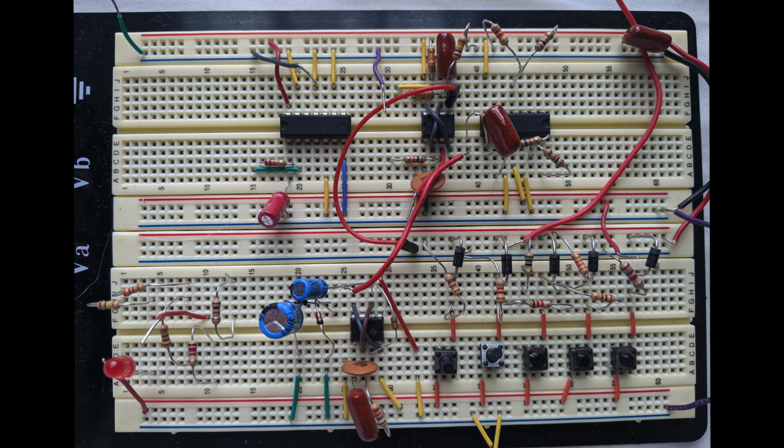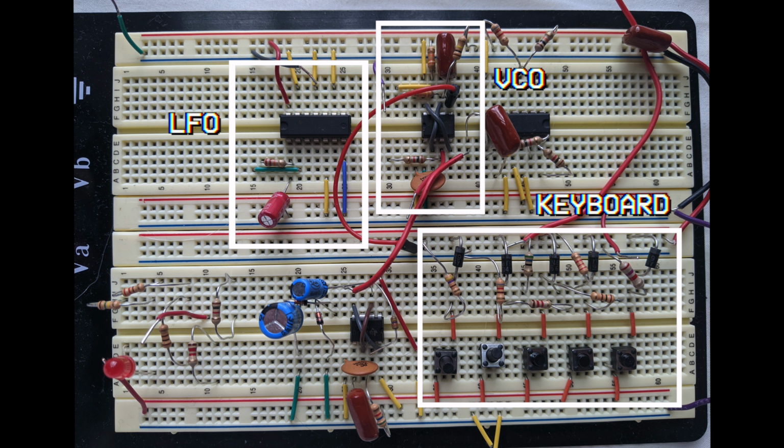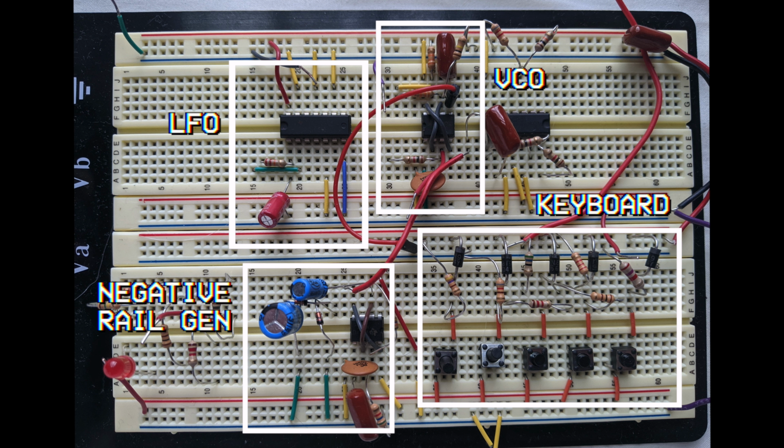We created the VCO circuit as well as the LFO circuit, though they only output a square wave, and we wanted a triangle wave for the LFO and a triangle wave option for the VCO. We built a voltage divider keyboard using 5 push buttons, though we had planned to expand this to 2 octaves. We also built a negative rail generator that creates a negative output from a positive input.